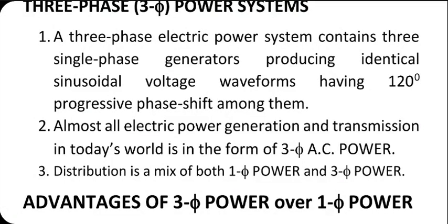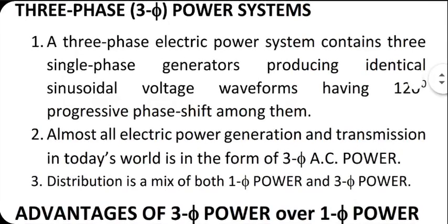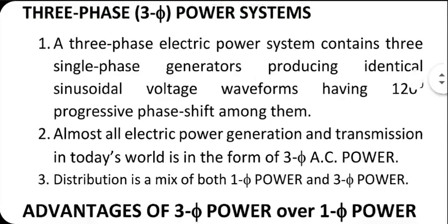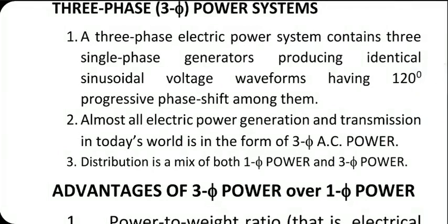If you had started with single-phase system, three-phase would not have been possible at all, even if customer wanted it. But if you have started with three-phase, single-phase can always be derived from the three-phase. You take only one of the outputs instead of three outputs. So it is good that we are starting the generation in three-phase. That way we are remaining open to the possibility of taking care of single-phase demands. Other way around, it's not going to be possible.